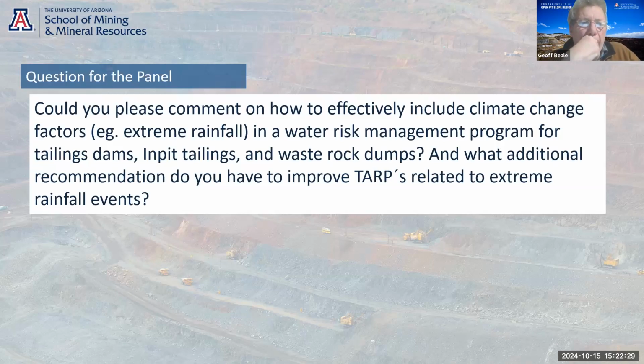And secondly, the rise in the tailings level is typically greater for an in-pit tailings, depending on how big the pit is, than for conventional tailings. So the buildup of excess pressure can be larger. You can end up with a tailings surface in the pit which takes a long time to get access to. It takes a long time to consolidate.